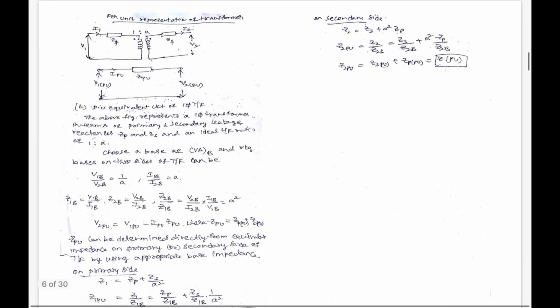There is an important derivation, the per unit representation of the single phase transformer. Per unit representation means that whether you move from the left side or the right side of a complicated power system network, you get the same values. Here is the proof. In this proof, V1 by V2 is 1 by a, and I1 by I2 equals a.